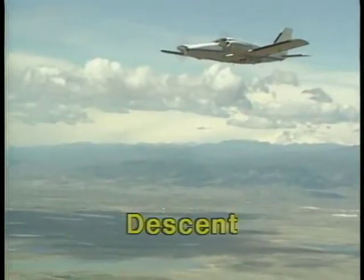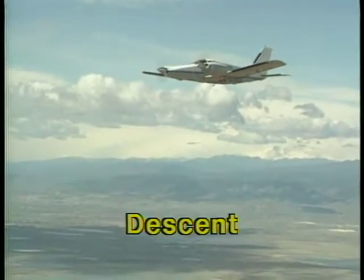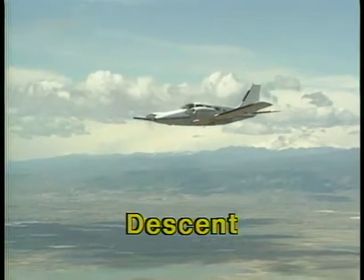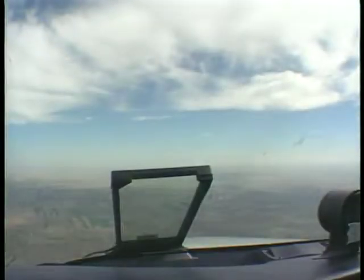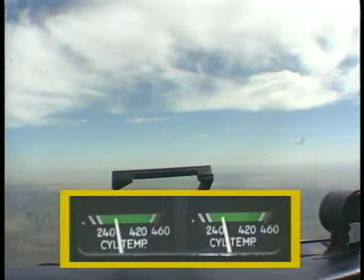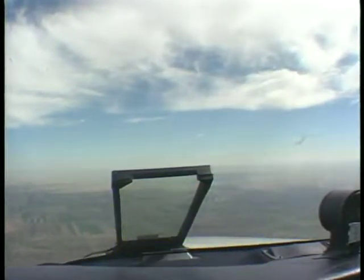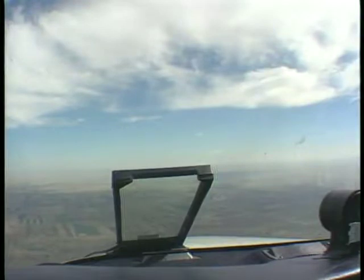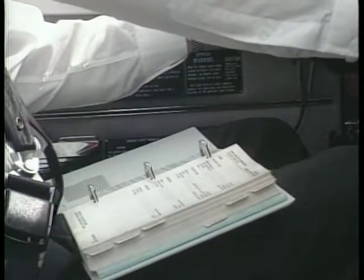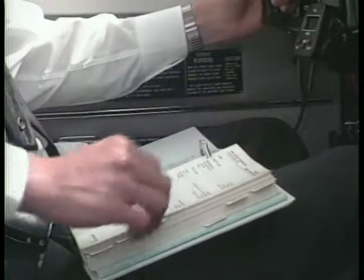Because of the increased speed and altitude range of a twin, you must plan ahead for the descent to your destination. A cruise-powered descent with its higher power setting keeps the engines from cooling down too rapidly. It also offers improved passenger comfort and ground speeds. During your descent, perform the appropriate checklist items and review the traffic pattern procedures.